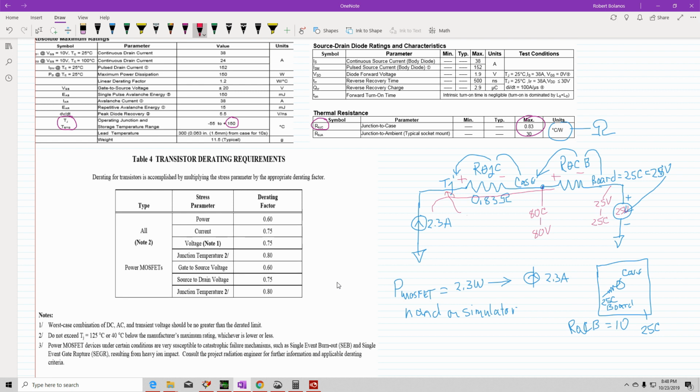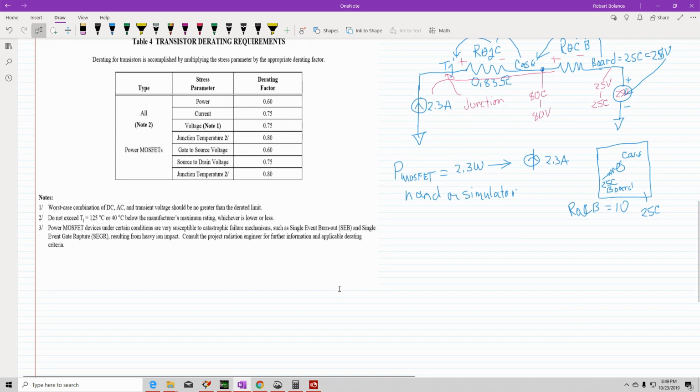Exactly what I had said yesterday, that it was getting hot. This thing is really burning, and if you were to let it run, you would probably see smoke. See right there, that's about 120, 125, so it's already exceeding the junction temperature. It's around 300 degrees. That's extremely hot.